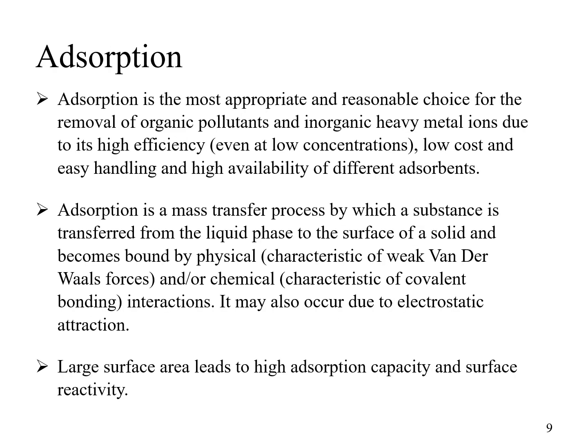Adsorption. Adsorption is the most appropriate and reasonable choice for the removal of organic pollutants and inorganic heavy metal ions due to its high efficiency, even at low concentration, low cost, easy handling, and high availability of different adsorbents. Adsorption is a mass transfer process by which a substance is transferred from the liquid phase to the surface of the solid and becomes bound by physical interaction characterized by weak van der Waals forces and/or chemical interaction characterized by covalent bonds, and it may also occur due to electrostatic attraction. Large surface area leads to high adsorption capacity and surface reactivity.